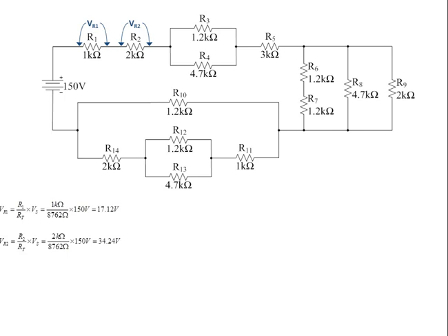Next, we're going to get the voltage across R3 and R4, which will be the same value as the two resistors are in parallel. So to do this, we put the resistance of this parallel section, which we again calculated earlier as RA, over the total circuit resistance and multiply it by Vs, and we get that VR3 equals VR4 equals 16.37 volts.